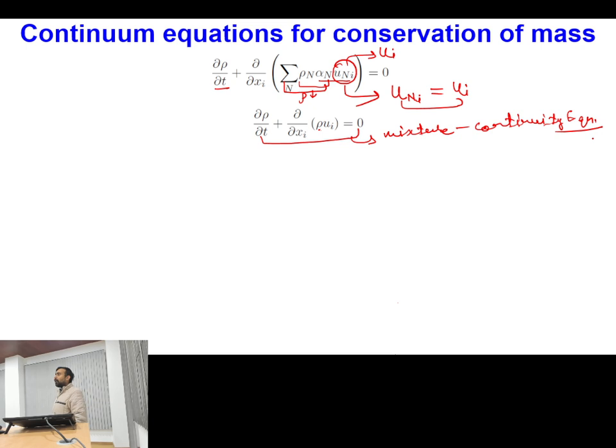Okay. So, later on, whenever we will be talking about the flow through pipes, in particular the bubbly flow through pipes, then we have to estimate how much pressure drop is happening in the pipe if a two-phase mixture is flowing. Okay, so there we will be doing the analytical solution by considering the homogeneous flow model. The homogeneous flow model is actually based on this assumption only.